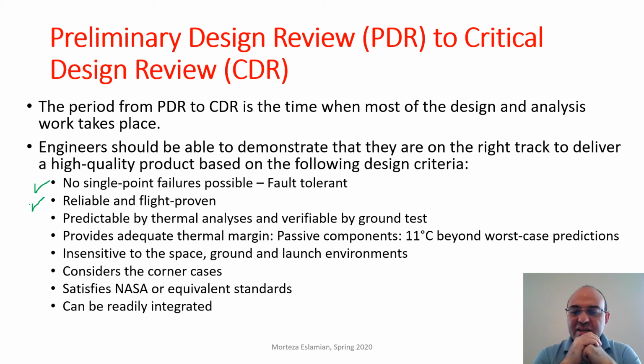They need to demonstrate that later they can actually test what they are designing for the spacecraft, and they need to provide adequate thermal margin according to the standards, and the solution should be insensitive to the space, ground, and launch environment. They need to provide a level of sensitivity, if something changes, how adaptable the solution will be. They need to consider the corner cases that we have talked about before, the most critical cold and hot cases.